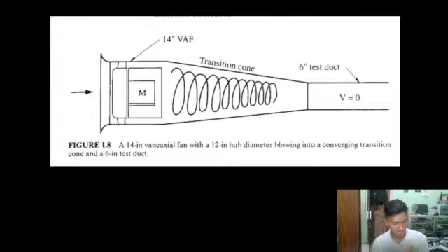Back in 1949, the designer tested a 40-inch axial fan with a 12-inch hub diameter, resulting in an unusually large hub-to-tip ratio of 86%, right? This was done because the requirements were for a small airflow in CFM and a high static pressure. A centrifugal fan would have been a better selection, but the customer insisted on the axial fan.